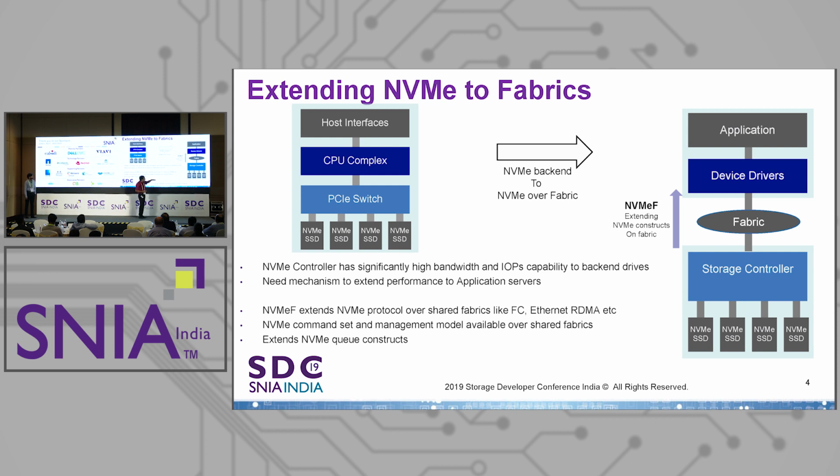So how do these NVMe SSDs work? They work on queues, and queues are dispersed across various cores. And parallel things can be written to NVMe. When we talk about HDDs, right? HDDs used to have this mechanical drive, and the protocol was written in such a way. But these NVMe SSD drives have the capability to have parallel IOs, and these IOs can come through a lot of queues, which I have told you, 64,000 queues and 64,000 commands.